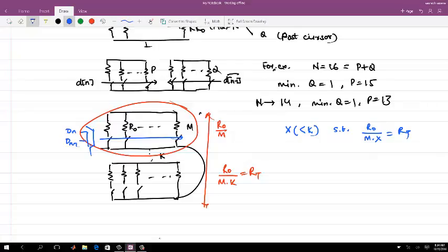Now within each cell, I will choose my equalization depending on the coefficient I want. The minimum of post or precursor is 1 out of M. So no matter where the process variation takes it, it will always maintain that particular ratio.